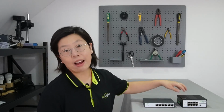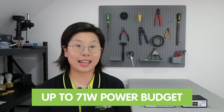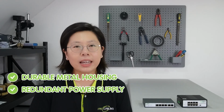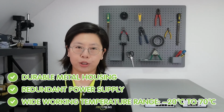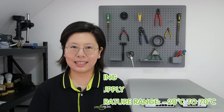Next to it, we have our 8-port PoE pass-through switch. This one supports PoE pass-through to draw power from an upstream PoE switch or injector while providing up to a 71 watts power budget and 30 watts power output to connected devices. It has a durable metal housing and redundant power supply, making it ideal for harsher environments, since it has a wide working temperature range from -20 degrees up to 70 degrees.